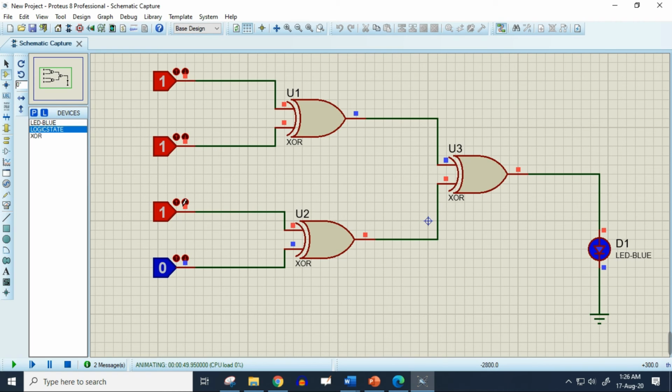At any given moment, if we consider the input and output together, the total number of ones should be even in case of even parity. That's why when all the input values are 1, so 4 ones, it is already an even number, so there's no need to give another 1 at the output.